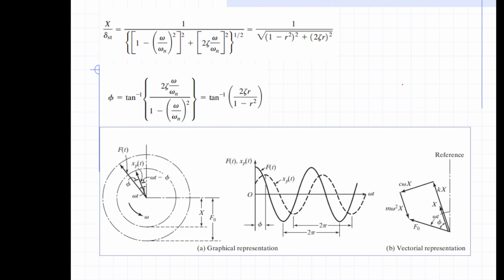So follow the process I just showed you earlier. You will find the ratio between the amplitude in the case of forced vibration and free vibration. This one you just put the force constant, but this one you put the force with frequency. Okay, and you want to find the ratio between these two cases.